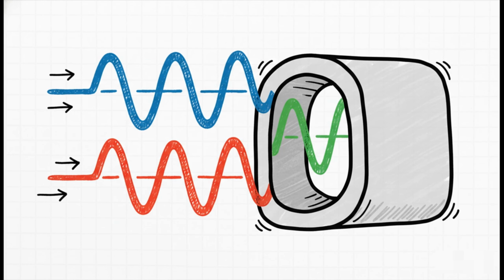And it's the exact same idea behind what we call band pass filters. You design the circuit to have its resonant frequency right in the middle of a range or a band of frequencies that you care about. Frequencies inside that band get to pass through with very little opposition, while frequencies that are too high or too low are blocked by high impedance. It's absolutely fundamental for signal processing.